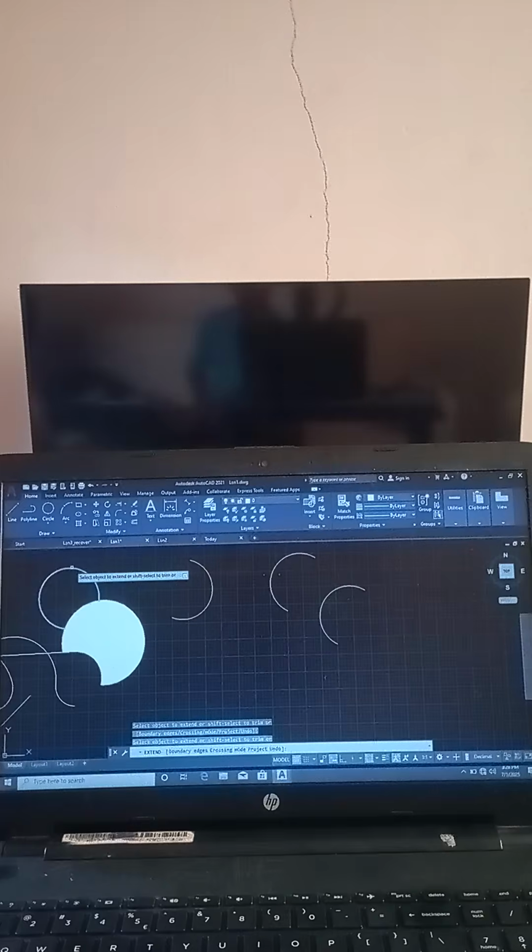But when I take it closer, it gets close to that. Watch what happened on this one, if I click on it, get this in closer, it links it up, it stretches it, extends it. Whenever it has a boundary, it's bound to extend. You can see if I remove it, it's gone. So if I take the key closer, and that is that. Now, why is that possible? Because the extend key was activated.